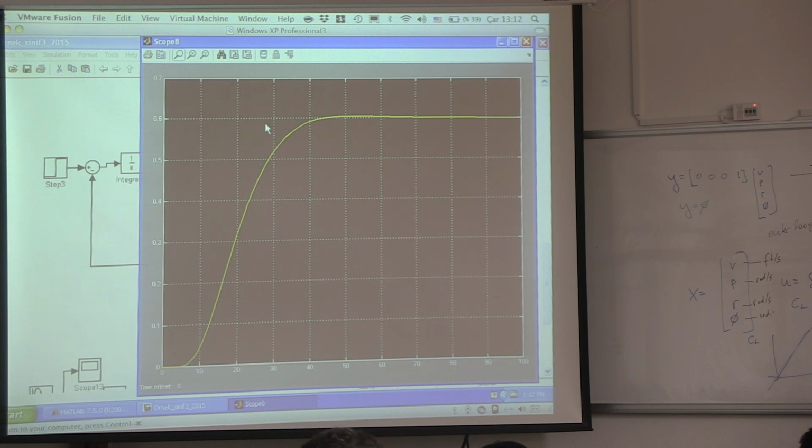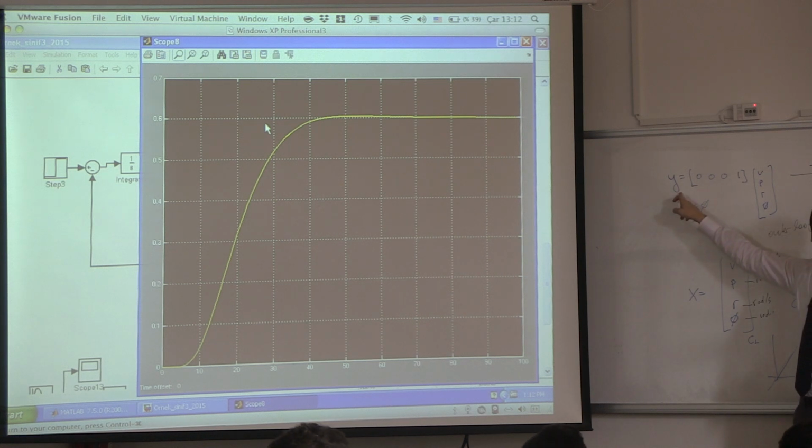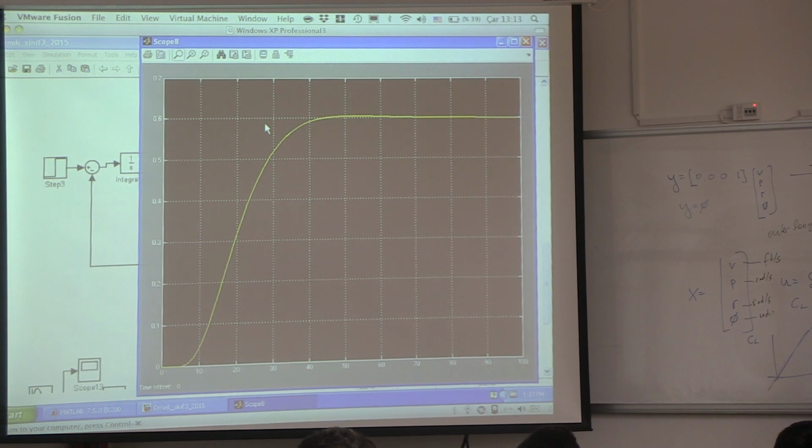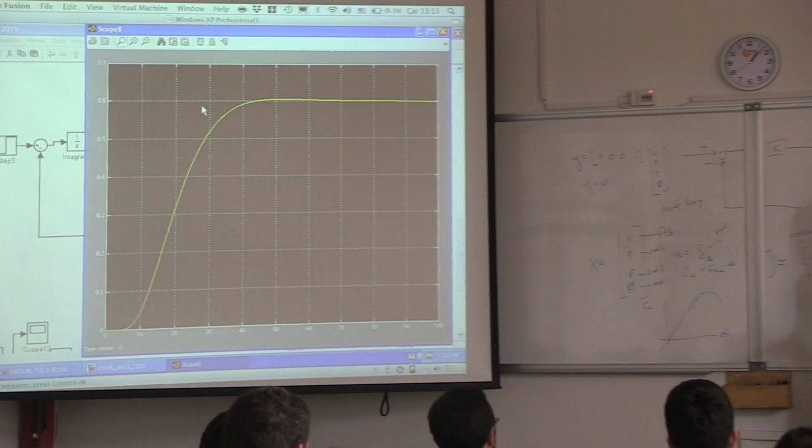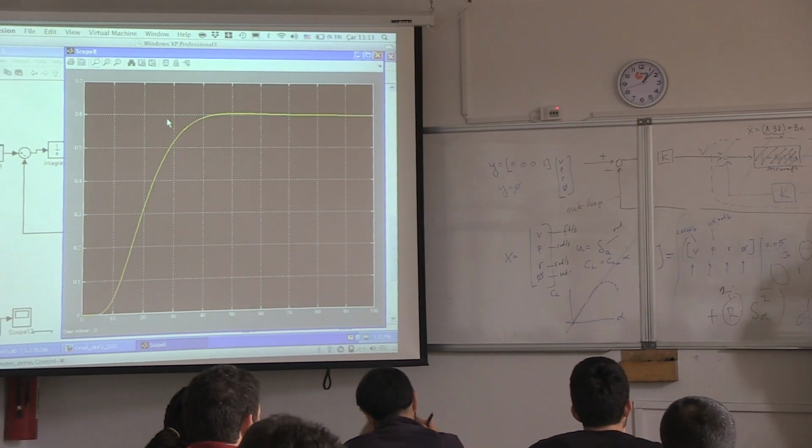And then in your homework, in your project, I put a third loop that is actually controlling another one. Because what you can do is you can put another loop over here. The command will be the velocity. Velocity is commanding theta, and theta is giving the input to the actual system with a stabilization loop, so that would be a velocity controller, okay, for an aircraft.